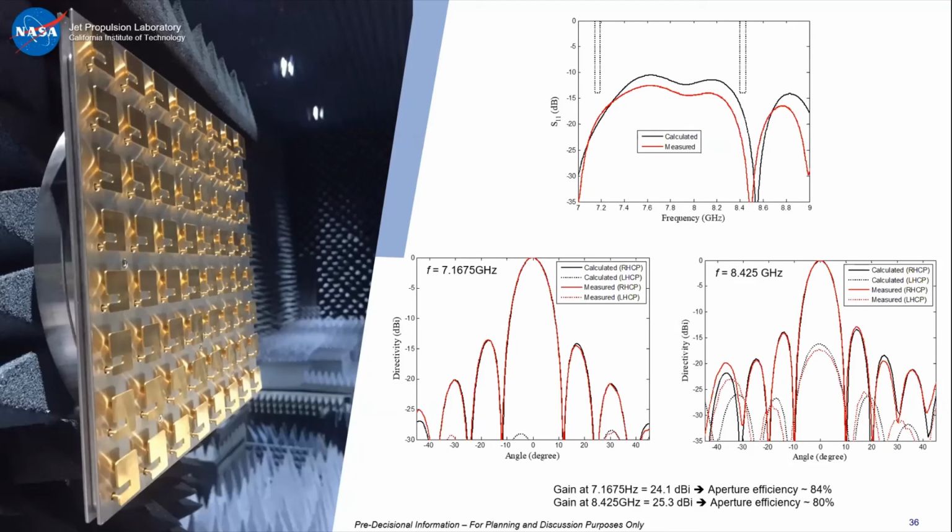Thank you, sir. There are a few more questions in the chat box. How do you choose which polarization to use when designing a spacecraft antenna? It's pretty straightforward. For telecommunication, it's always circularly polarized for space to Earth, because we don't want to be impacted by the orientation of the spacecraft. If you have linear polarization, you need to make sure that the transmitting antenna and the receiving antenna are lining up. So you don't want to be dependent on the polarization. And circularly polarized is also less sensitive to rain, for instance.